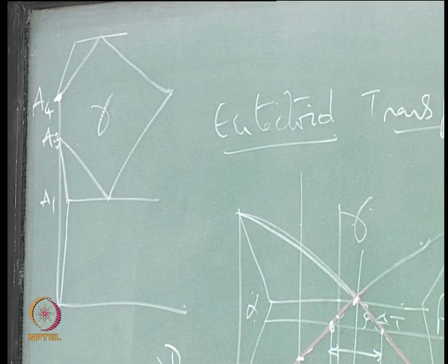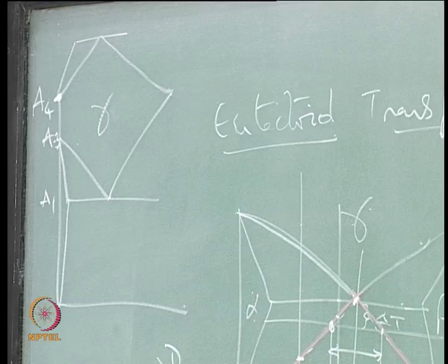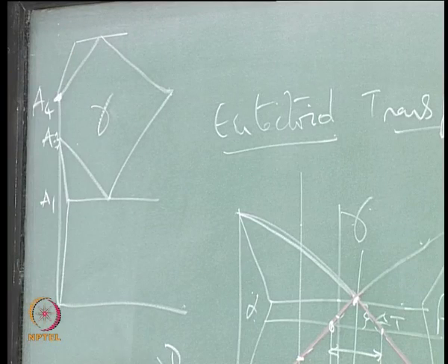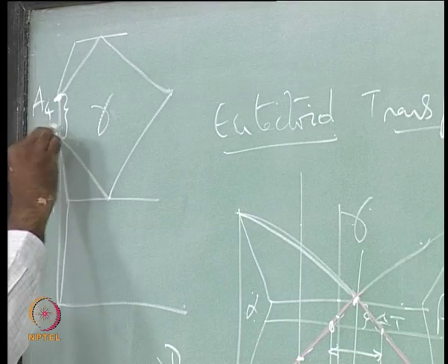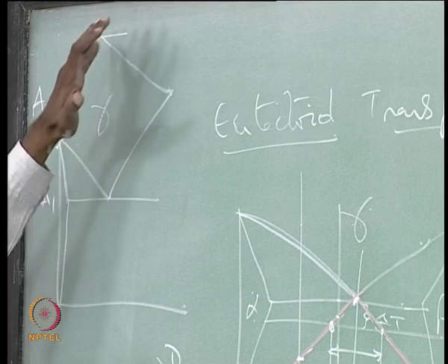So that A2 is the magnetic transition. And that A4, that is what you can actually see, how carbon stabilizes the austenite. The moment you add carbon, you see A3 is decreasing, A4 is increasing. As I add more and more carbon, A3 decreases and A4 increases. That means pure iron gamma is stable only between these two, 910 to 1400, whereas at around 0.8% carbon or so, you can see it extends from here to here.